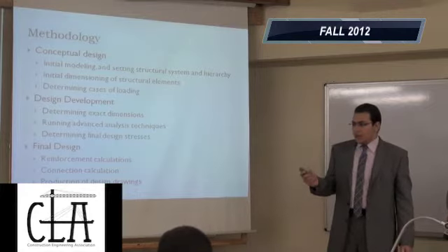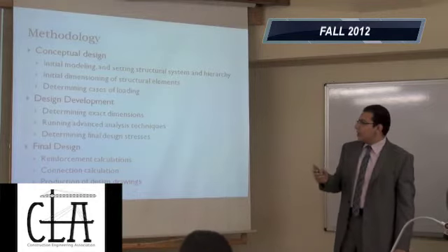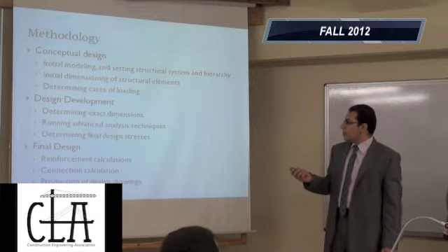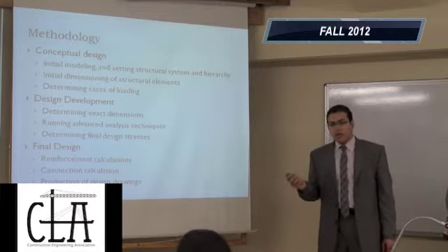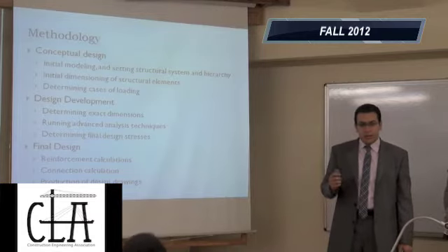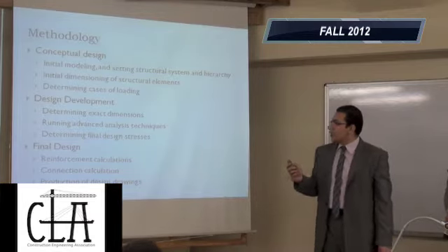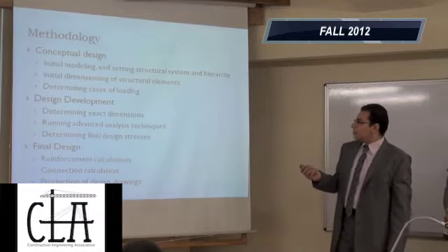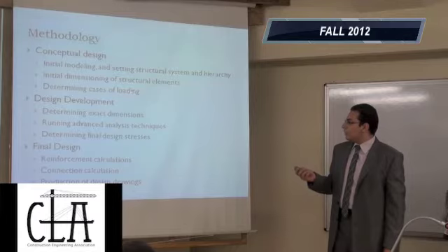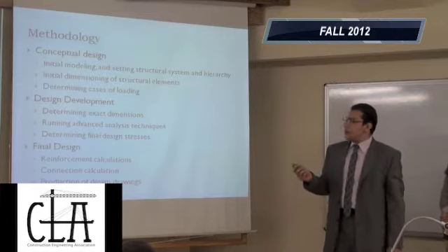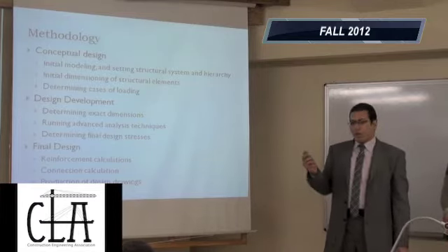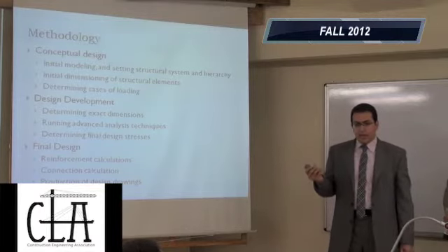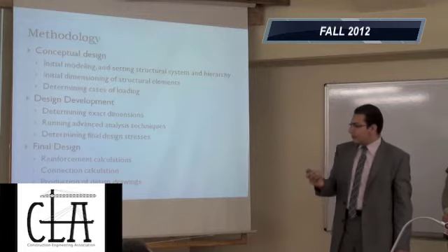It means which structural elements are going to carry which others. In the second step, the initial dimensioning of structural elements, we are going to assume some reasonable values for the cross sections and the lengths of the structural elements to start the modeling. In the third step, we are going to determine the cases of loading. In other words, we're going to figure out, after analyzing the system, what the governing cases of loading are.